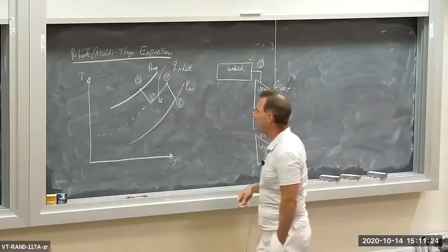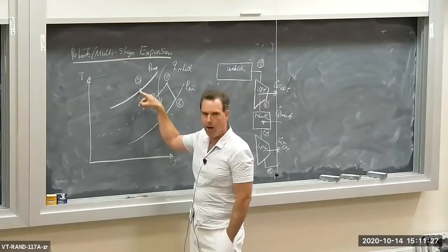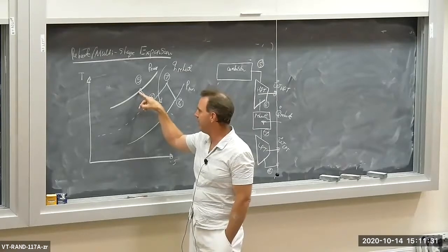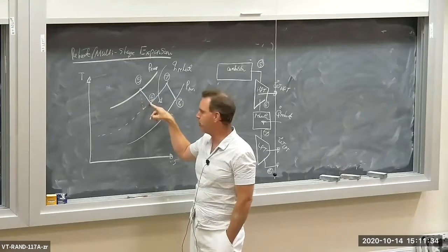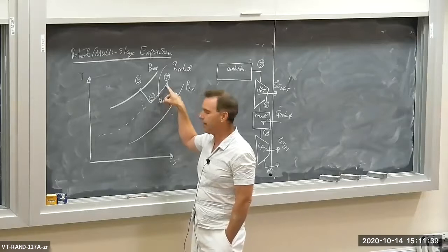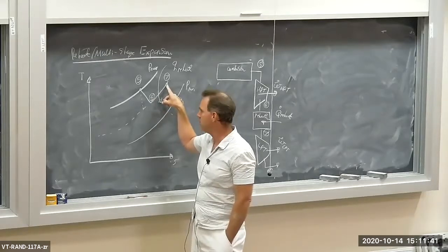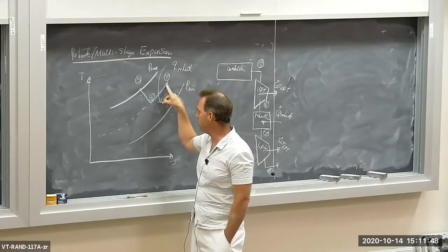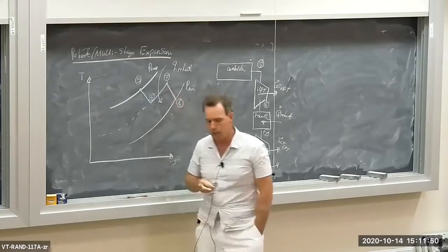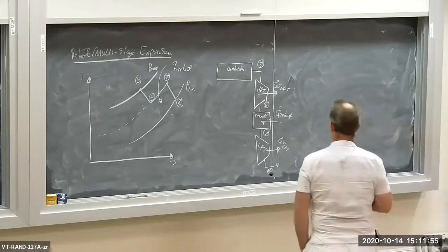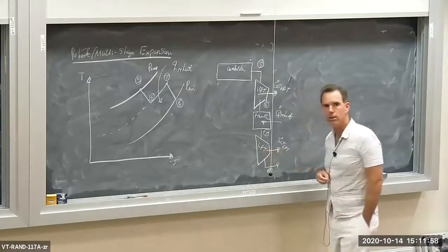So let's go over this one more time. Hot products of combustion, hot air, from the combustor into the high pressure turbine, our first turbine. Add heat in a heat exchanger called a reheater. Add fuel, burn it, add heat. Heat up the air, heat up the exhaust, the products of combustion. Then expand, finish the expansion process in a second turbine called the low pressure turbine, LPT.